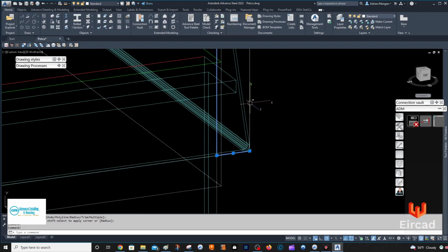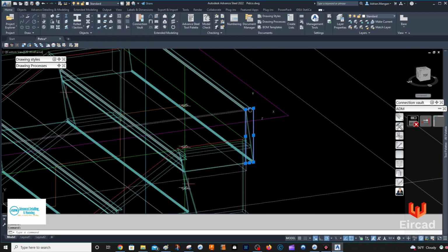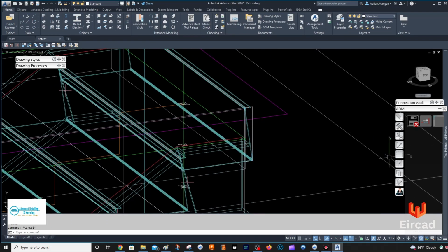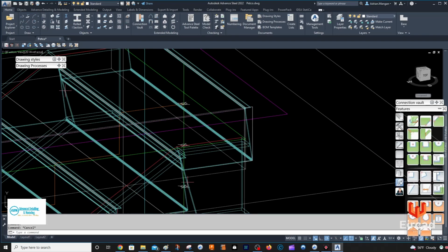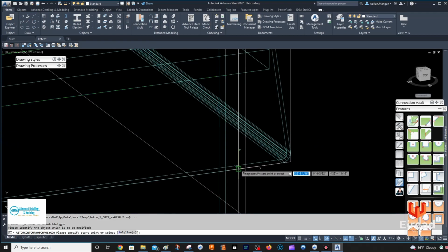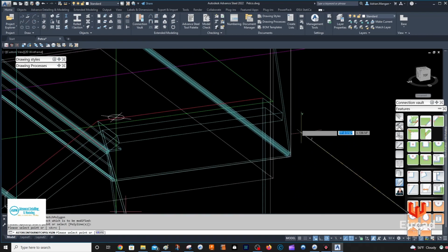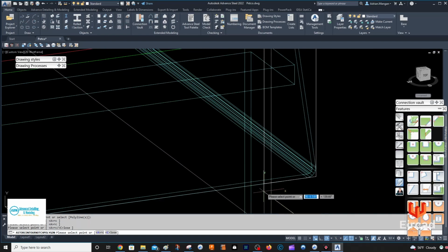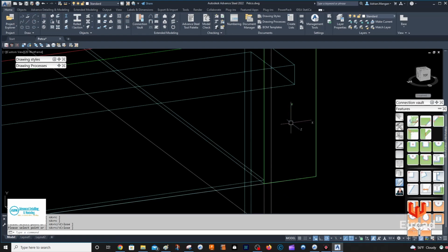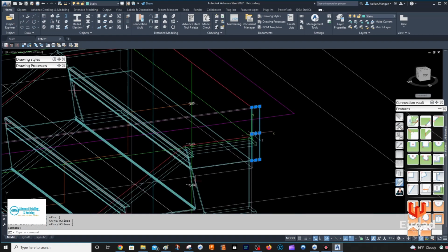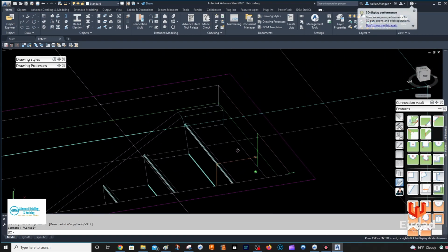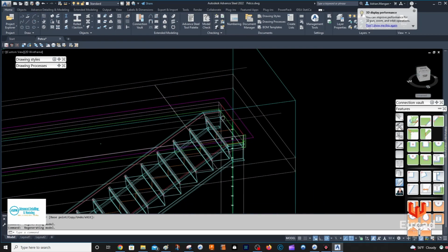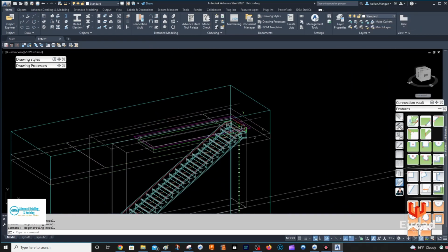And then that's going to be where you cut the plate, and then I can drag it over and back. So again, go back to your features, and we'll do the polyline one in case this is not a rectangle, because I'm not sure. It should be. I came straight down, I went straight up, so now let's cut that. And then what we can do then is you can just drag this over and back as you need to. So you can make it a little bigger, a little smaller, and you don't need to do it inside the macro. And now you have that step there.